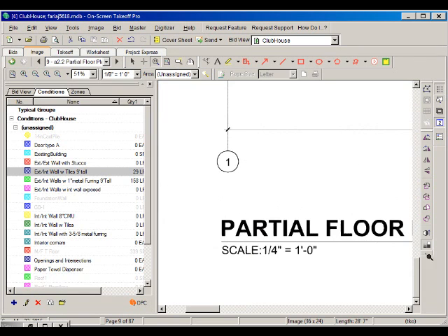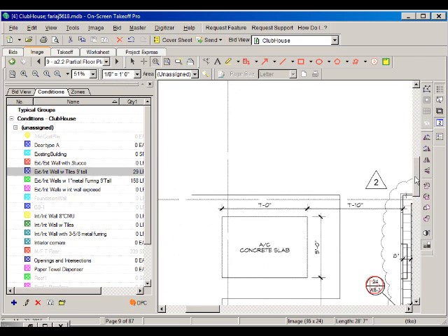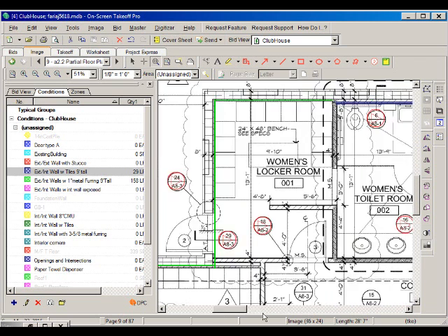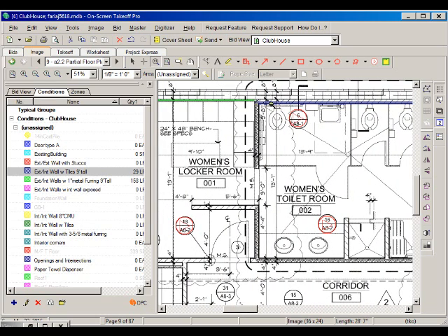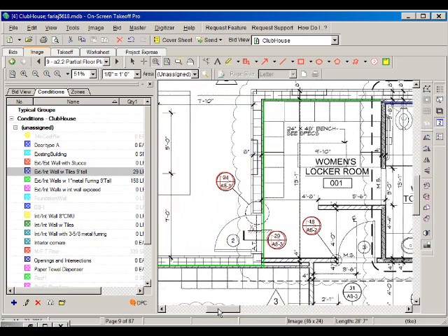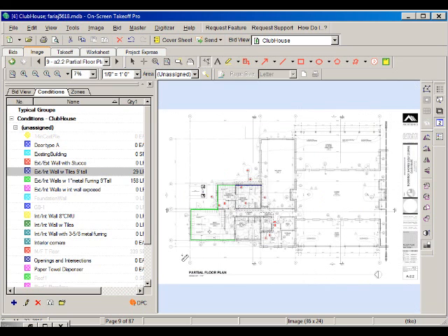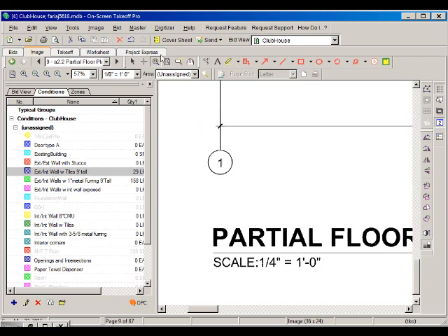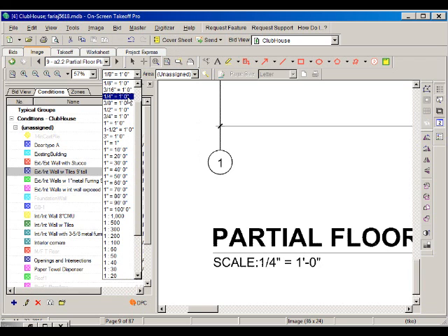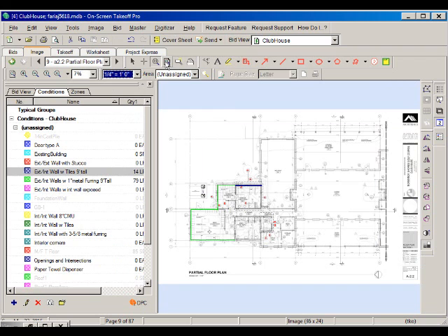Yeah, the scale doesn't seem right. The reason I noticed that the scale is not right is because when I draw the 4-inch line, it does not seem to match the architect's 4-inch line. Of course, what I should have done is to verify the dimensions on vertical and horizontal scale, so I would have noticed that my scale is off. So now that I realize that, the problem is solved by changing the scale to the correct scale. So this will be 1/4 of an inch to a foot.